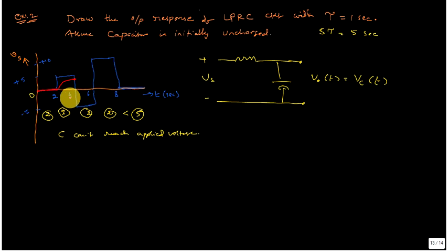This value you need to calculate, and when the capacitor reaches this value, again you are applying minus 5 volts as constant, that too for 2 seconds of time. So whenever you are applying a constant voltage, the capacitor moves towards that voltage exponentially, but it requires minimum 5 time constants, and you are allowing only 2 seconds. So it also does not reach minus 5 volts, it reaches only a part of that voltage, and again it is exponential but with negative slope.